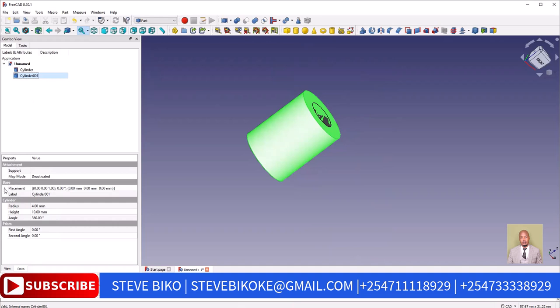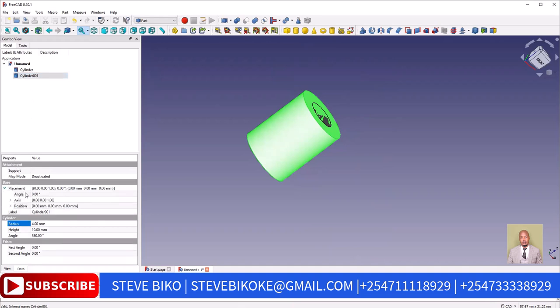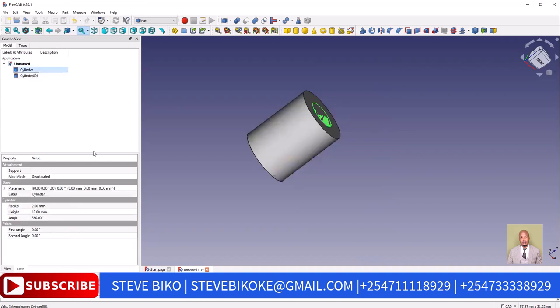At the base, you can click on the placement. You can see the angle positions. Then again, you click on the cylinder. After the base, there's a cylinder where you can now adjust the radius, height, or angle. So we've changed this one from 2 to 4. Then we go back to the other cylinder.